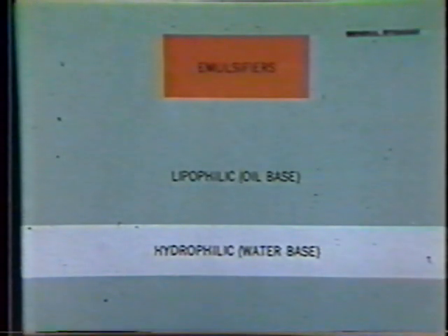Hydrophilic, water-based emulsifiers can also be used as contact emulsifiers. But more often, the emulsifier is diluted and sprayed under pressure. It acts as a low-energy scrubber in removing excess penetrant. The washing action stops when the spray is stopped.